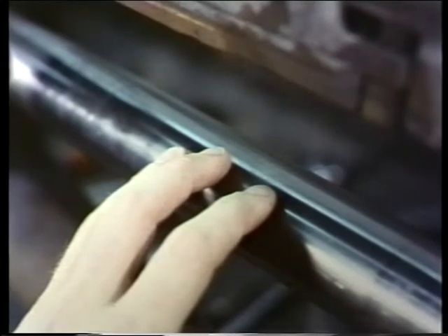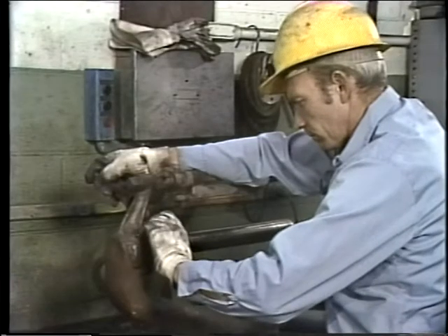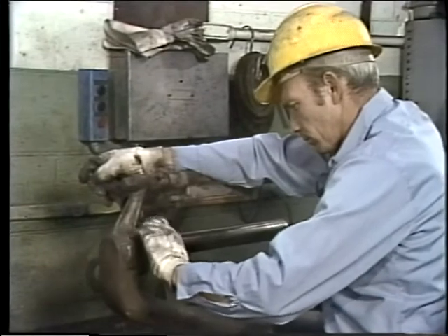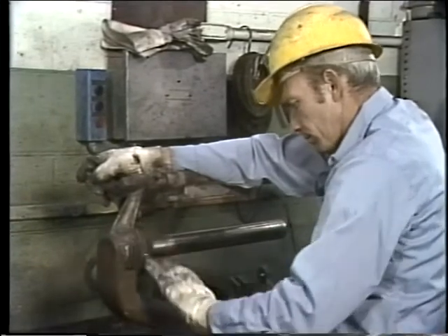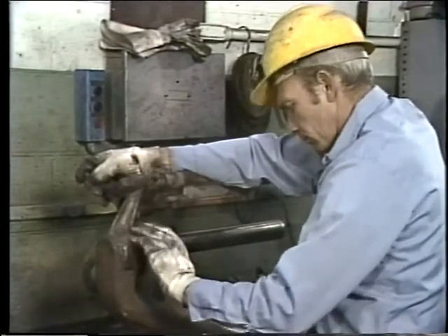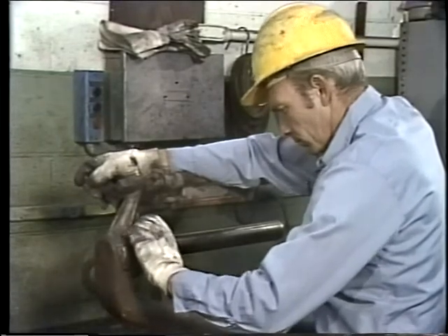When the element is off, a close inspection of the feed tube will reveal any wear which might have allowed unnecessary leakage past the packing. You might satisfy yourself with a close visual inspection, maybe a careful feel for scratches or roughness. In this example, no problems are found, but the feed tube will be pulled off so the gasket that seals it can be replaced and the housing can be inspected.